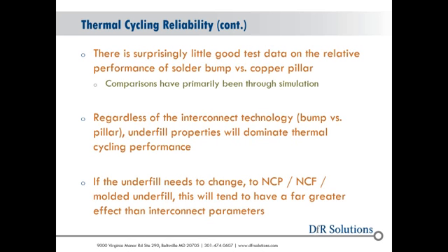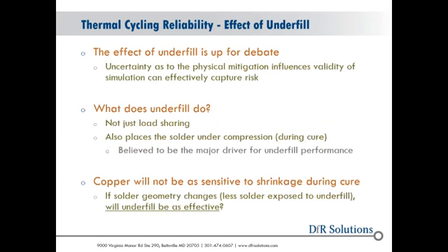So let's think about underfill for a second. What does it do? Well, it shares a load. If I stuff more material between the flip chip die and the BGA substrate, they're all going to share the load, so there's not much load on any one individual solder joint or flip chip joint. But if you run the calculations and compare it to actual performance, it's not just the load sharing. It doesn't correlate. The load sharing would maybe double the lifetime, maybe triple, but you can see 10, 20, 30x improvement in reliability by using underfill.